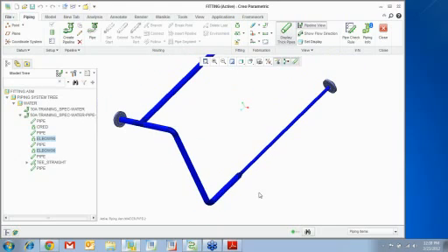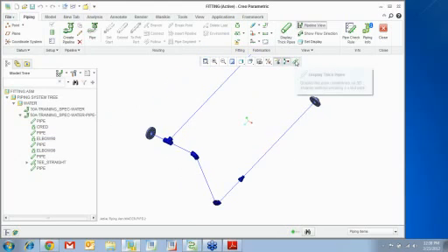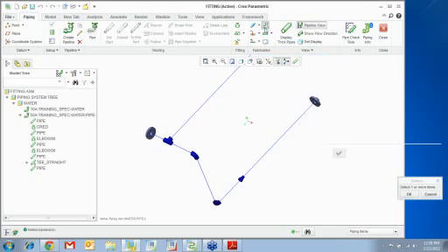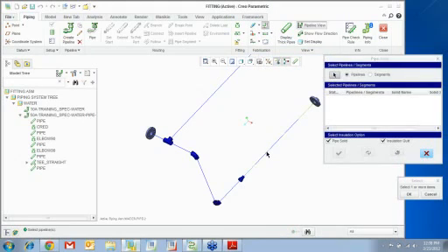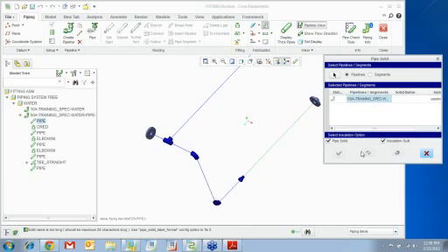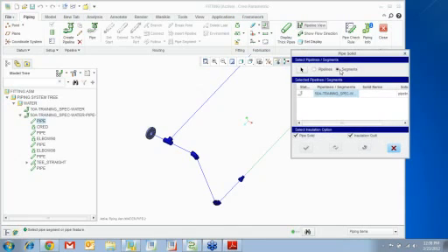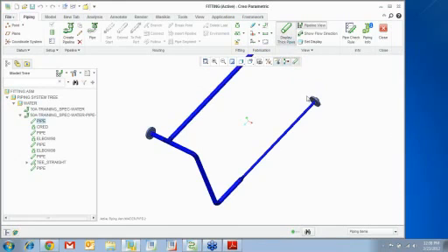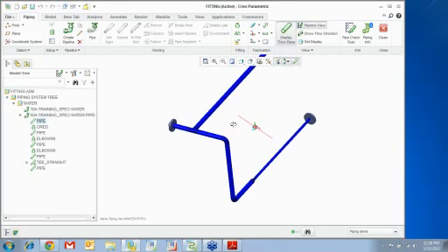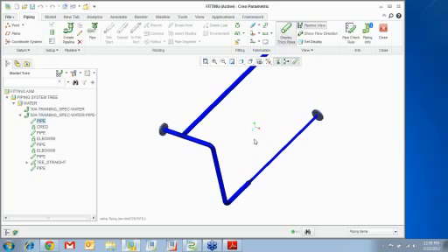Right? So people who don't want to use schematic, but want to route their pipes with a certain spec, can always use this. Since welding, creating spools, creating a solid pipe, I pick that and say okay. It's going to create a pipeline wherever you need. So there you have it. This would be a kind of spec-driven pipeline.